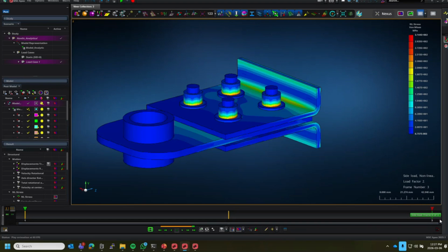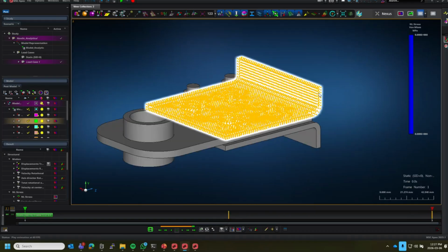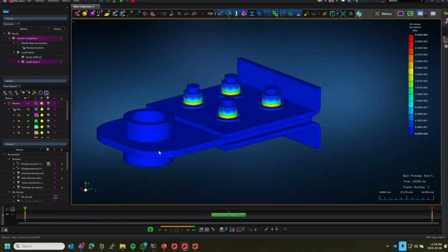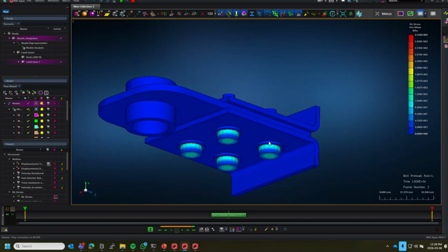And what you'll see is there's 3 steps. The first one is the model right at the beginning. So before anything is applied, that's that initial stress-free state, and all of those settings are being applied at that step. So I then go to the one after this one, for argument's sake. And at this point, it's just too sensitive. Okay. So at this point, you see the stresses are kind of reasonable, 300 MPa and so on.